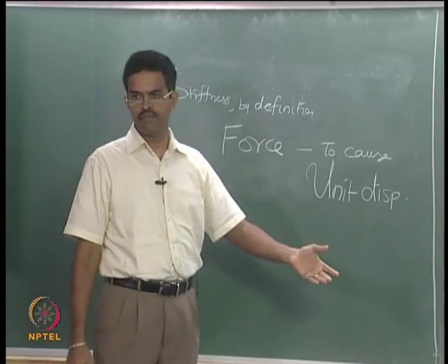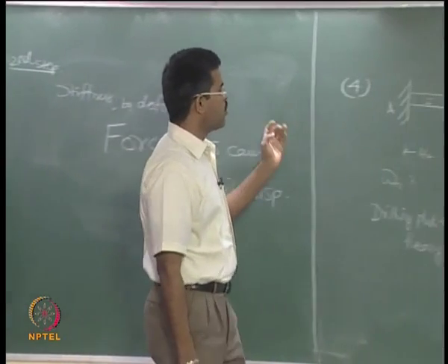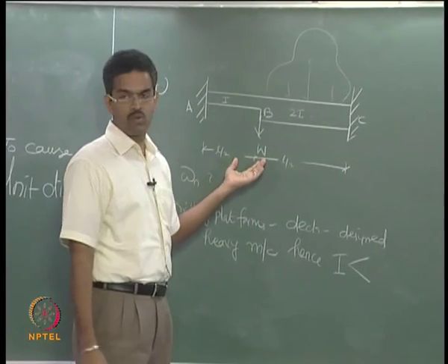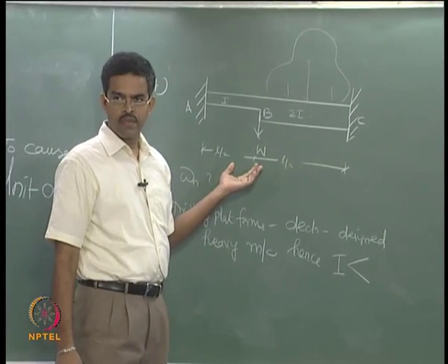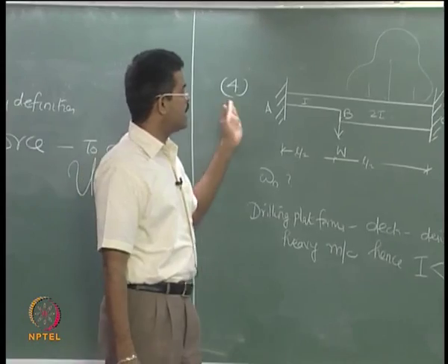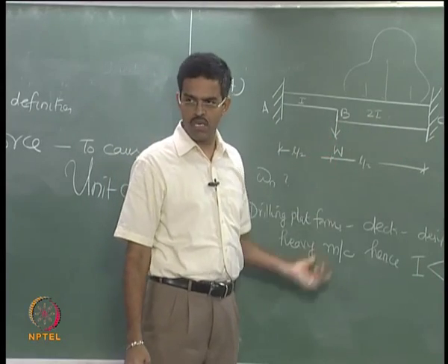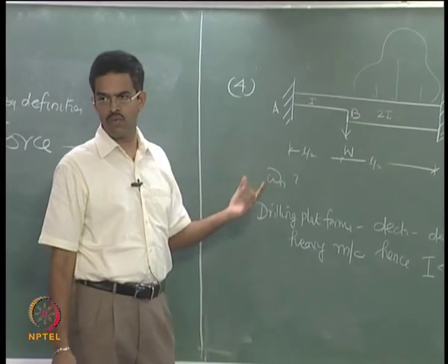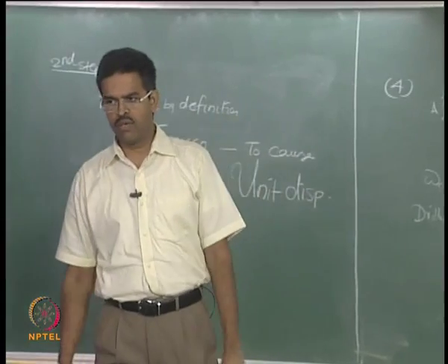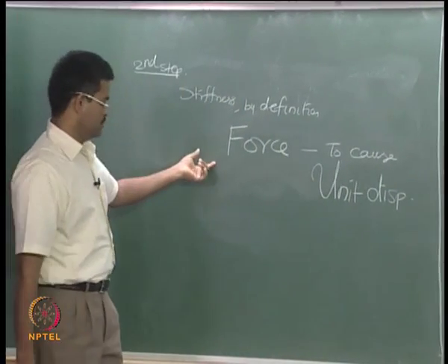this whole beam. Why am I looking at the stiffness of the whole beam? Because the mass of the whole beam is known to me. If you know the stiffness, being an idealized single degree of freedom system model, I can easily find omega n, which is root of k by m. So I am interested in knowing the stiffness here.